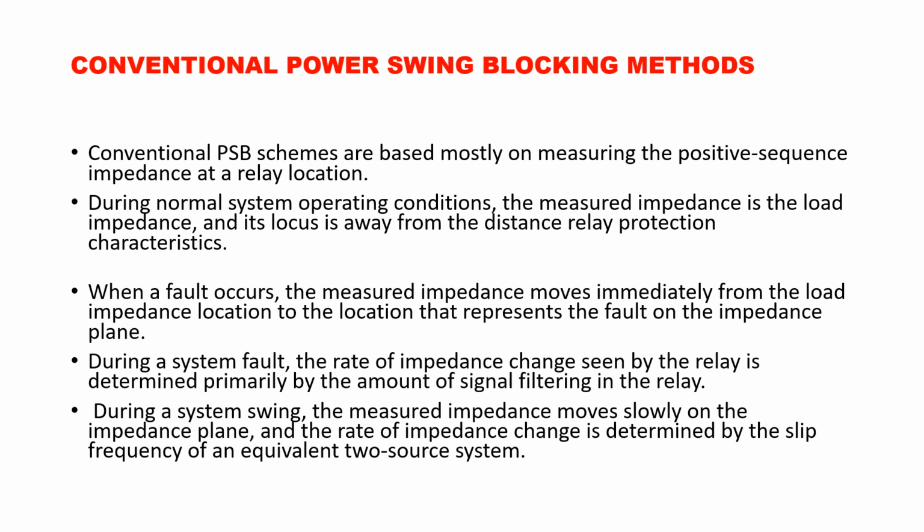As soon as the load point, or the measured value of impedance, touches or comes closer to the largest relay setting, third zone or fourth zone, the relay starts measuring and sensing that there is a fault, and after a certain time the relay will give a trip command. So this is the basis of everything in this one.